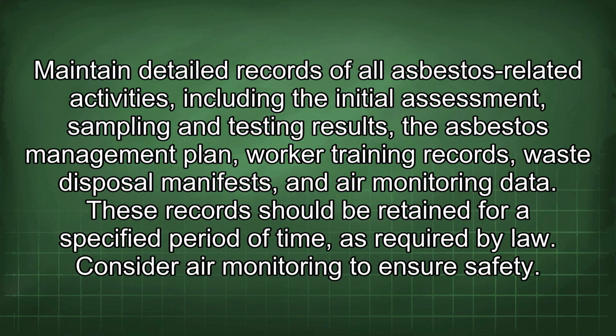Maintain detailed records of all asbestos-related activities, including the initial assessment, sampling and testing results, the asbestos management plan, worker training records, waste disposal manifests, and air monitoring data. These records should be retained for a specified period of time as required by law.